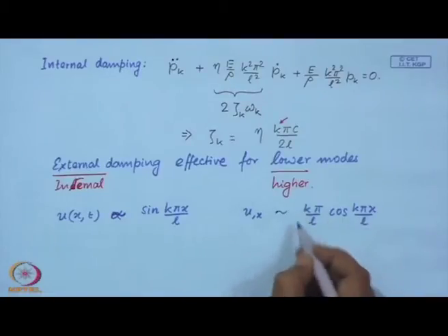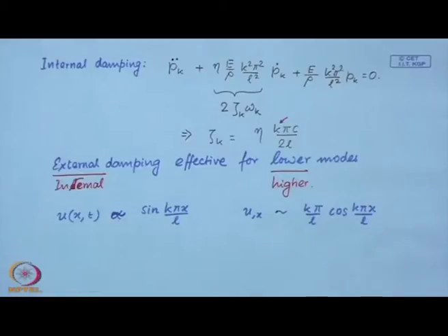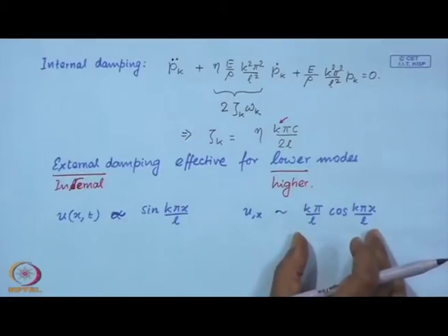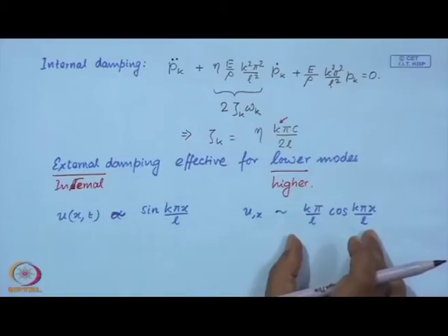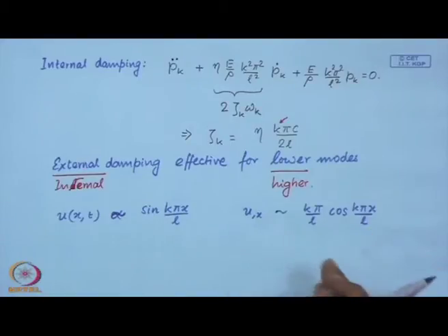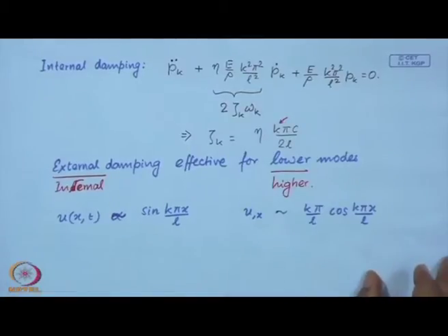So, higher the value of k, higher is the contribution from this strain rate term. So, for this reason, higher the mode, higher will be the effectiveness of the internal damping.